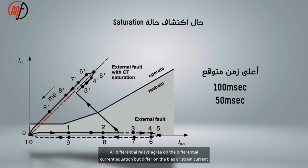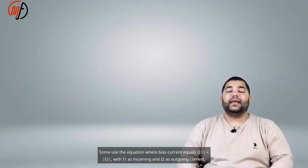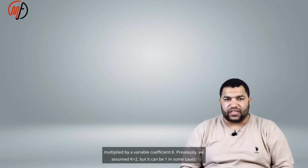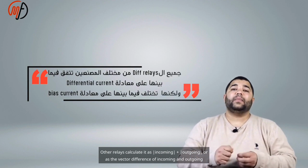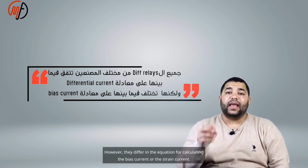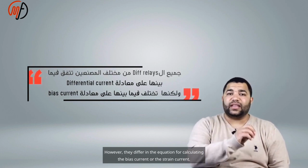All differential relays agree on the differential current equation, but differ on the bias or restraint current equation. Some use the equation where bias current equals I1 plus I2, with I1 as incoming and I2 as outgoing current, multiplied by a variable coefficient K. Previously, we assumed K at 2, but it can be 1 in some cases. Other relays calculate it as incoming plus outgoing, or as the vector difference of incoming and outgoing currents. However, they differ in the equation for calculating the bias current or the restraint current.